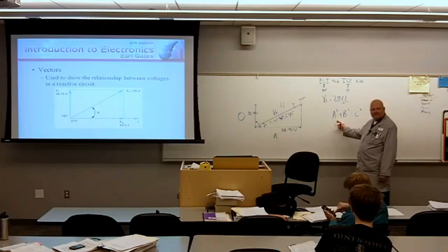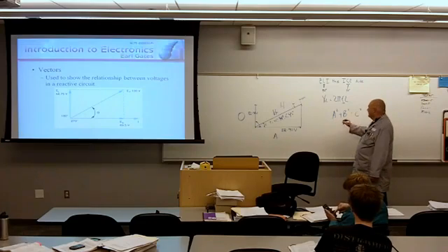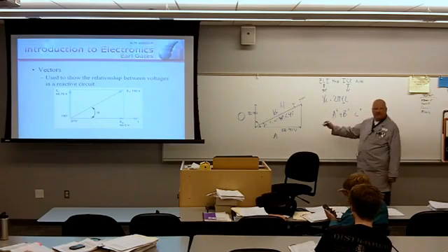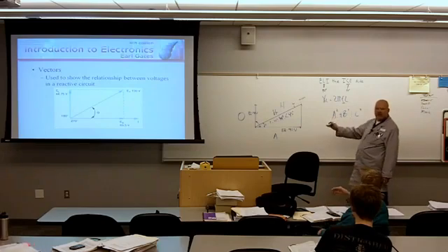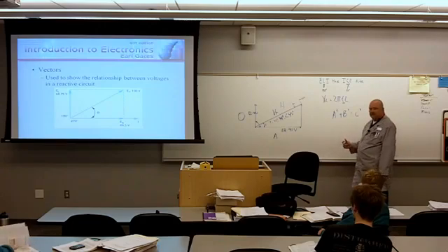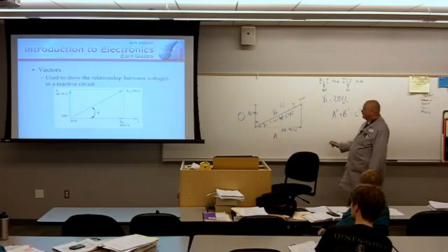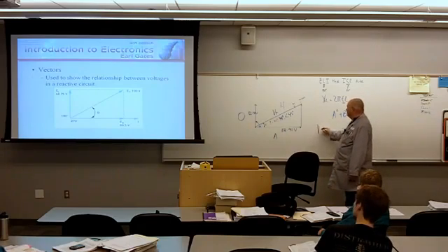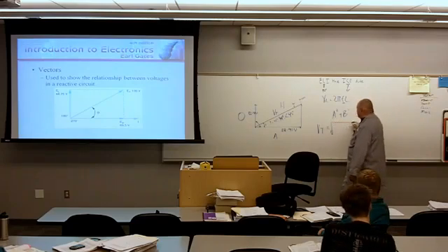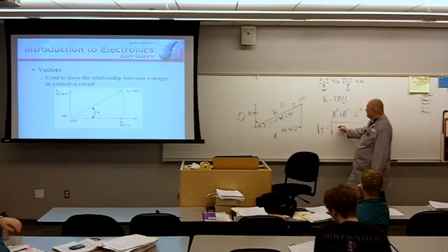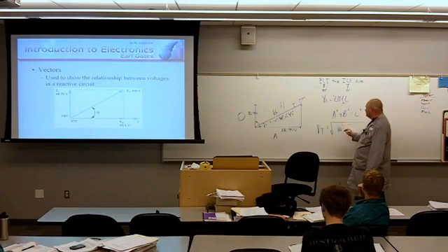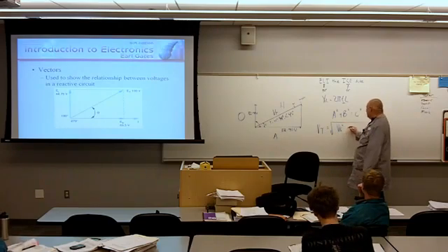This is the Pythagorean theorem. Now, we know that what we could actually do is replace these values with electrical values. And that's what we're going to do. And using algebra and reorganizing this formula, we're going to calculate that voltage total is equal to the square root of the voltage of the resistor squared plus the voltage of the inductor squared.